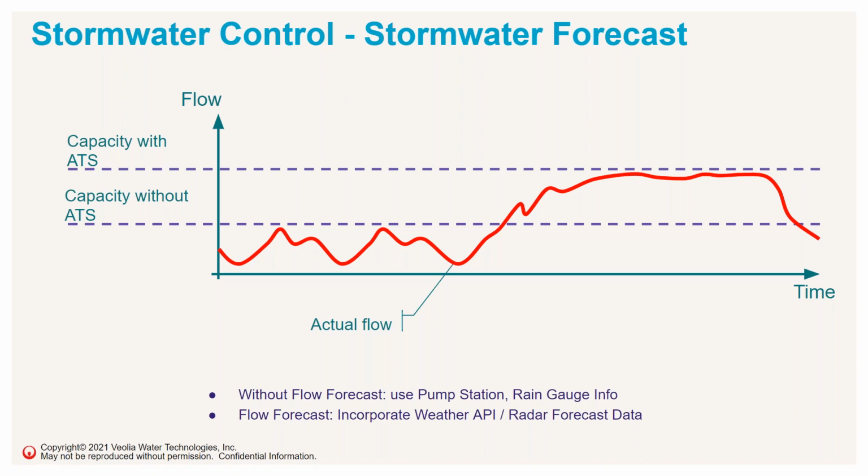It could also just be a rain gauge from somewhere up in the system, which would be enough of a warning that we know the water is in the sewer system, which means it will eventually arrive at the wastewater treatment plant. So you can incorporate both data series, one or the other according to availability, and then maybe be able to react earlier.